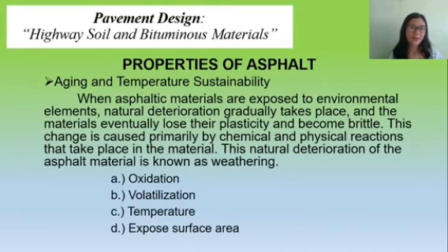So next we have the aging and the temperature susceptibility. When asphaltic materials are exposed to environmental elements, natural deterioration gradually takes place and the materials eventually lose their plasticity and become brittle. This change is caused primarily by chemical and physical reactions that take place in the material.